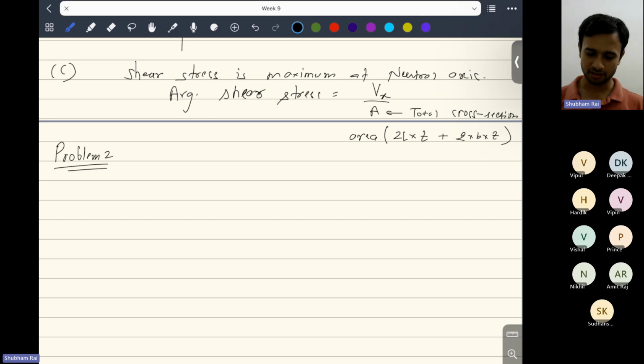So in composite material, since they are perfectly bonded, in-plane displacements, which in the case of a beam means the longitudinal displacement U, will be continuous with respect to thickness, because the materials are perfectly bonded.